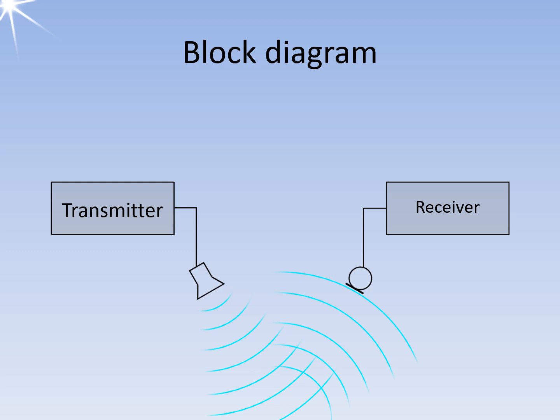The radar transmitter often has a pulse power in the kilowatt range, in the past even megawatts. The receiver must be able to process signals in the picowatt range. The ratio of received power and transmitted power can be about 1 to a quadrillion. For comparison, the chance of winning the jackpot in the lottery is about 7 million times larger.